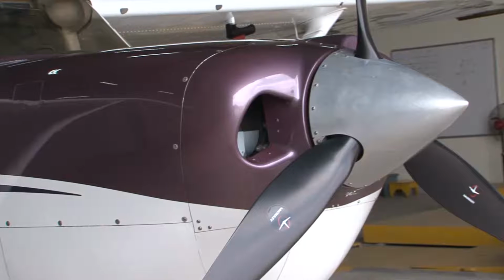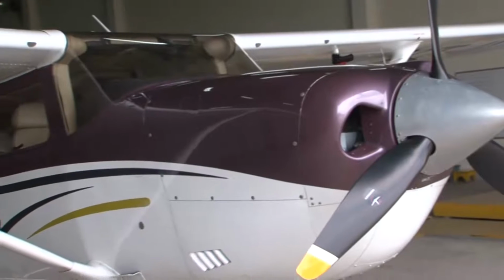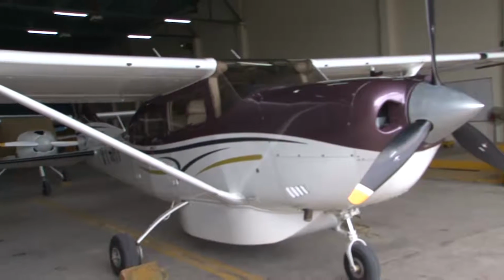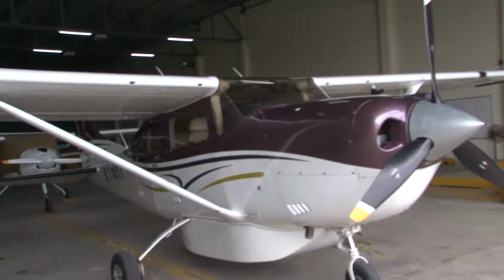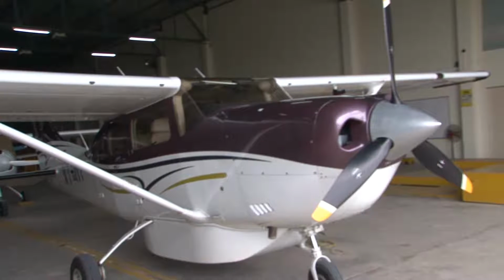Now again, recalling what we have been talking about in the classroom, we are talking about thrust loading, then power loading. Since this is an IC engine propeller driven aircraft, we will not talk about thrust loading, so we would like to know what the power loading is for this aircraft. And the power loading for this aircraft is 12 pounds per horsepower. Again, you can check the statistical data that this will fit into whatever has been reported in the literature. So I repeat, the power loading is 12 pounds per horsepower.